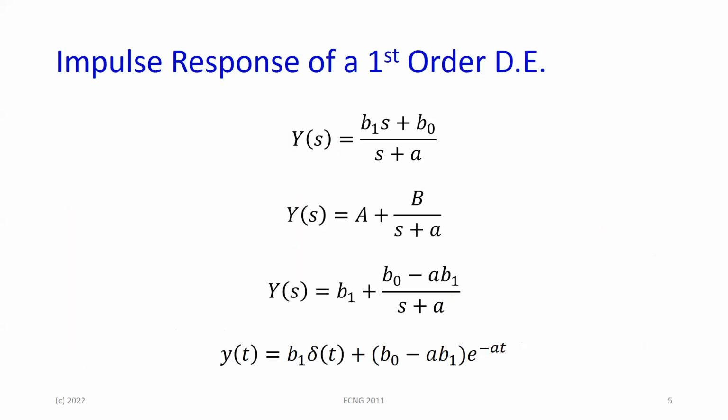And this is where you do your little algebra. If it is of that form, then you have to find the inverse Laplace. And one of the things we said is that the order of the numerator and the denominator, that the order of the numerator has to be less than the denominator. If not, then you have to divide at least once, right? So this is all a bit of revision here again. So this is not, the order of the numerator is 1. The order of the denominator is 1 here. So the system is not proper.